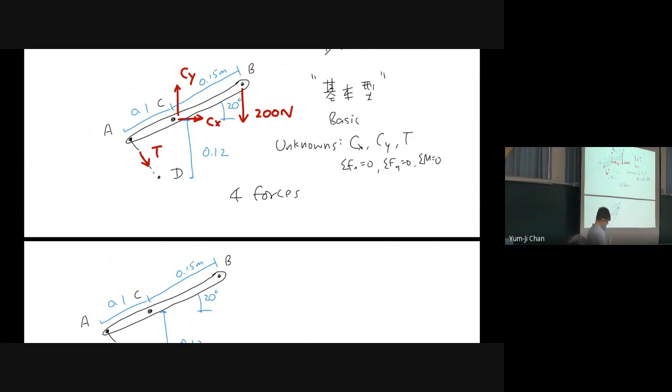Of course, we have T, Cx, Cy, and that 200 newtons. But they all act on only 3 points of the body. So it is a 3 force body.